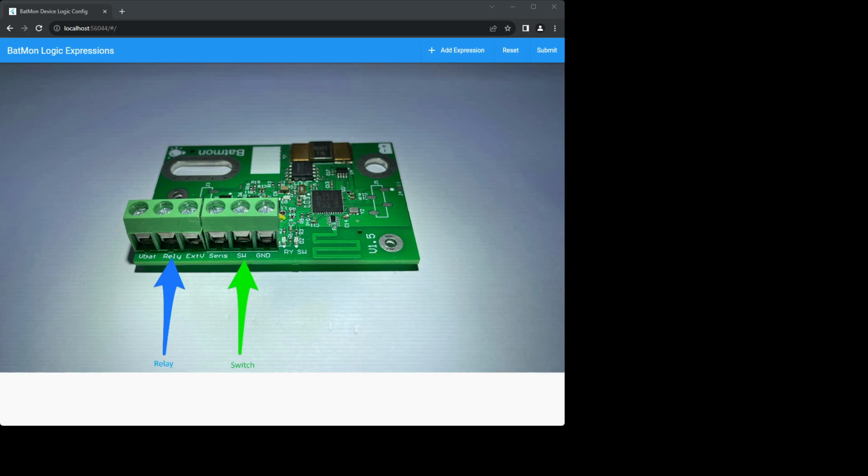This, when on, gives 3.3 volts out, and when off gives 0 volts out, so could control a solid state relay, or we could make it an input pin and use that to observe the state of some external equipment, but more about that later in another video.